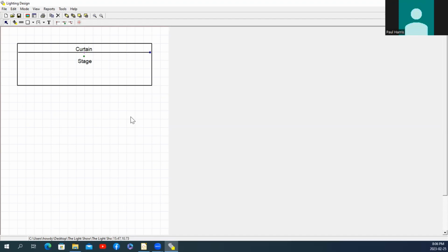in your system. So we're going to use the lower toolbar and click on another one of those squares. This time, it's the sideways black line called Add Bar Mode. Now you can go down on the stage and left-click, and a bar will appear. This is where you will be hanging your lights. If you've been to the theater or been given notes, you'll know where these bars are located up in the ceiling. I happen to know that this one's about 10 meters from the back wall and roughly 10 meters long.